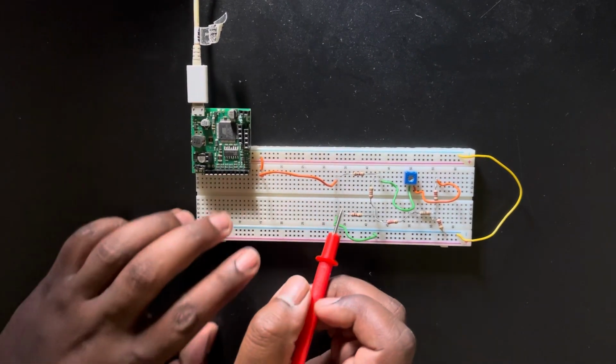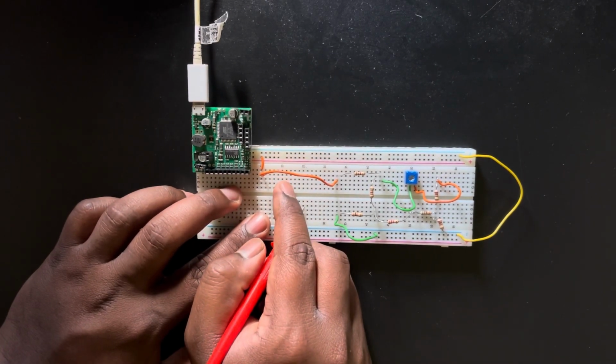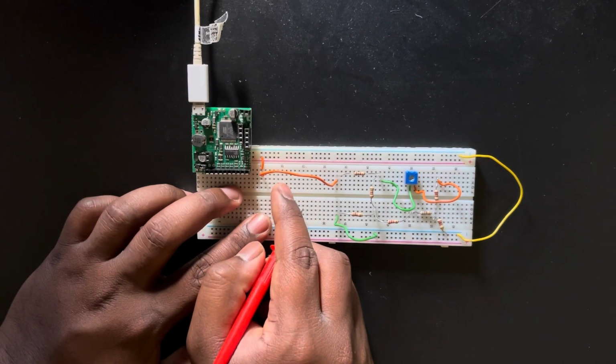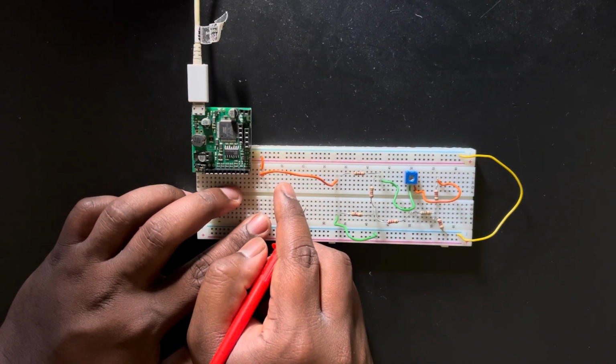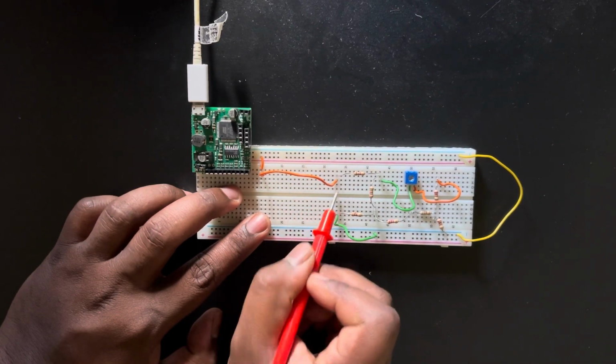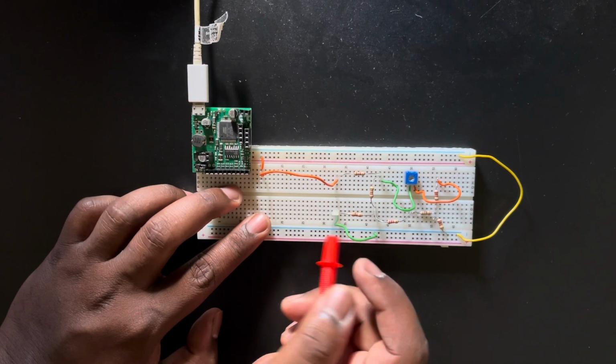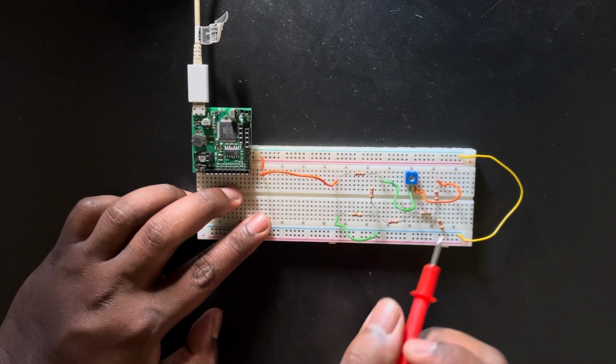In order to measure the current, you just disconnect this one, and then set your multimeter probe to 20 milliamps, and measure the current through it, just like you did before. Like, how do you measure the current with the help of a multimeter, right? You just perform that, and after that you have to measure.